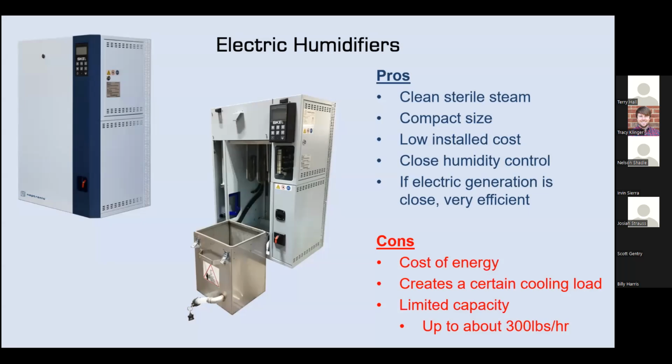So with electric humidifiers, these are going to be the majority of what we manufacture, just because they're so versatile and they fit most applications. The big benefit here is you're heating water to produce steam. They're compact and easy to install. You need a drain, you need an electrical hookup, you need a water supply, and you need somewhere to put the steam.